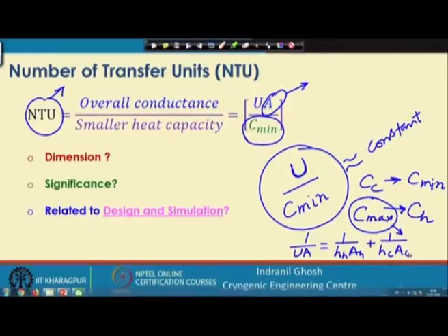And since here in this one we have another term R W, that is the wall resistance, we may consider it, or sometimes we neglect this term. Now, what we find is that C mean is directly controlling the NTU in this relation, but the other one, C H, will also have an influence on this overall heat transfer coefficient by controlling this H H term. When there is a change in C H, that will change the H H, and that will in turn change the U A, and that will in turn have an effect on this overall NTU.